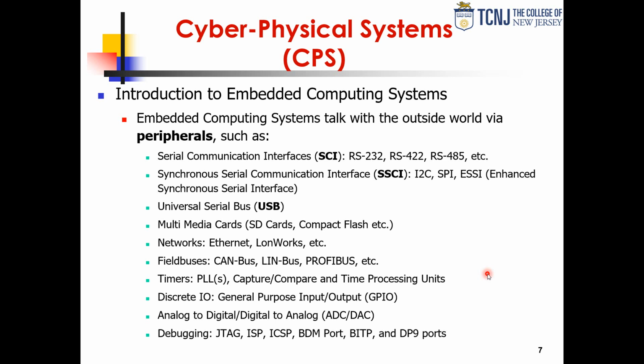When you're going off board in a wire fashion, USB is becoming the workhorse of embedded systems, if you're going to connect board to board. The latest standard of USB supports peer-to-peer communications. It was conceived with a host and device, not the same master-slave idea, where the device was sort of the slave in the arrangement. But it's more sophisticated than anything like SPI or I2C. You have hosts, hubs, and devices. You can essentially form a star topology, like a network.